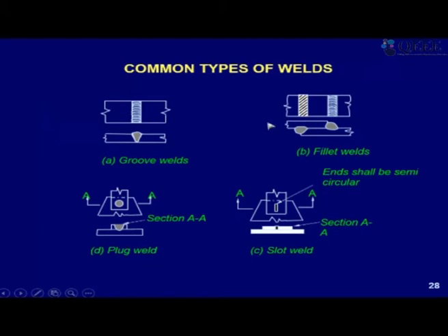Okay, I think there may be pictures here. So this shows you how we cut a V-shaped groove in these two plates. There are two plates which are actually butting, but we grind it and make a V-shaped groove, because depending on the thickness, my weld electrode may not penetrate the thickness of the plates to be welded. So if the plates are anything more than 3 mm, then welding cannot melt a metal which is thicker than 3 mm. Okay.